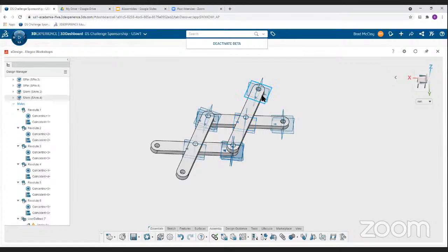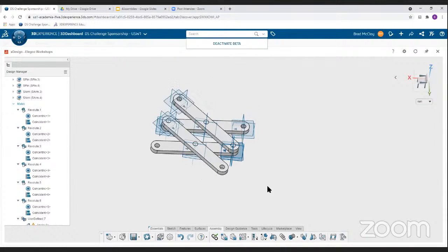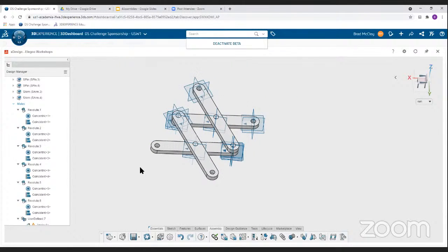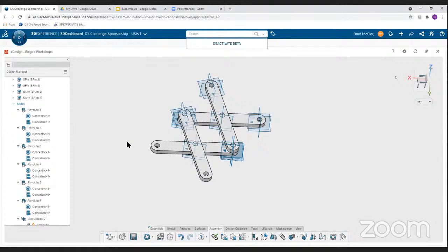But anyways, if you want, you could cascade more of these to make the scissor lift go higher. And what it ends up being is, with a little bit of motion in this way, you can see how much higher the scissor lift moves. Ideally, what we want to do is make these two, let's say, tangent to a base plate, or do something to constrain these to a table and float this arm and get our constraint a little more complex that way. But I think this gives the idea. So I think that's a quick introduction to mates that will allow you to go on.